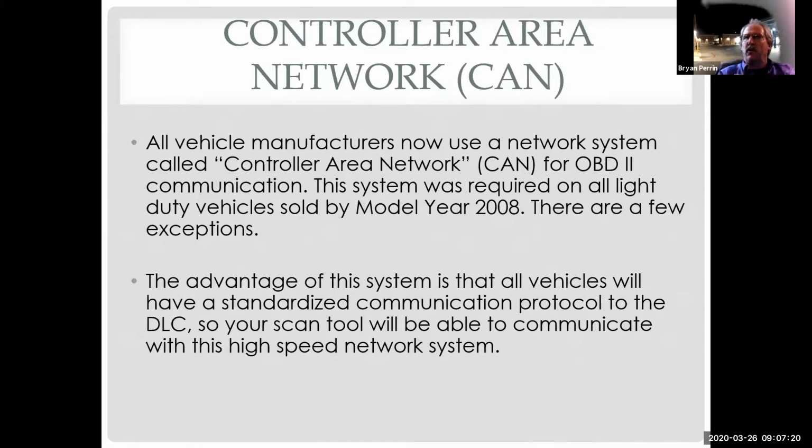On my Toyota, it'll do that in under 50 milliseconds. So at under 50 milliseconds, that's extremely fast data transfer. Matter of fact, my per PID rate's about 18 milliseconds on my car.